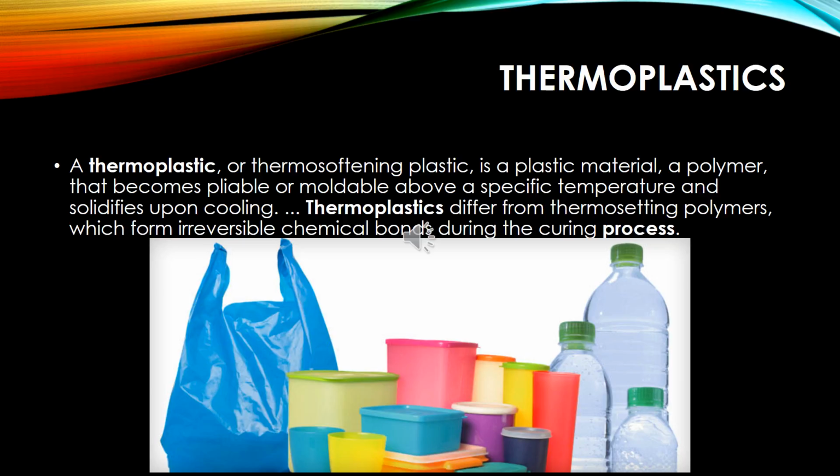When it comes to injection molding, it's easy to misunderstand the relevancy of thermoset and thermoplastic materials. For starters, both thermoset and thermoplastic polymers can be injection molded. The primary difference applies after the injection mold cycle, when the molded plastic cures. During injection molding, plastic is heated and then injected into a metal tool. In order to physically get to the cavity, the molten plastic must first pass through a series of tunnels and entry points known as sprue, runners, and gates.